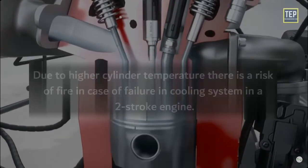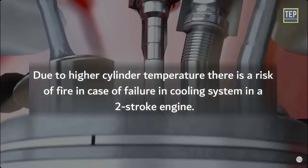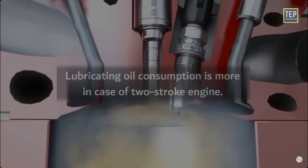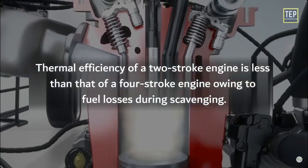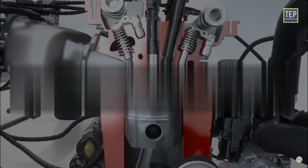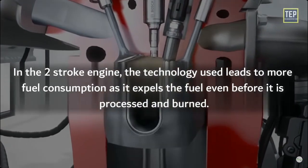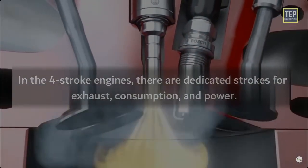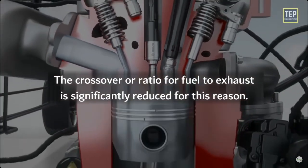Disadvantages. Due to higher cylinder temperature, there is a risk of fire in case of failure in the cooling system in a two-stroke engine. Lubricating oil consumption is more in a two-stroke engine. Thermal efficiency of a two-stroke engine is less than that of a four-stroke engine owing to fuel losses during scavenging. In the two-stroke engine, the technology used leads to more fuel consumption as it expels the fuel even before it is processed and burned. In four-stroke engines, there are dedicated strokes for intake, compression, power, and exhaust. The ratio of fuel to exhaust is significantly reduced for this reason.